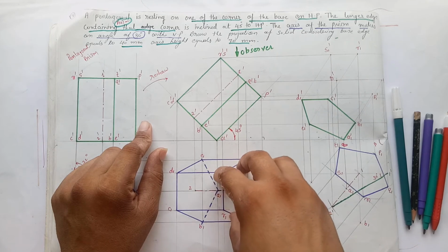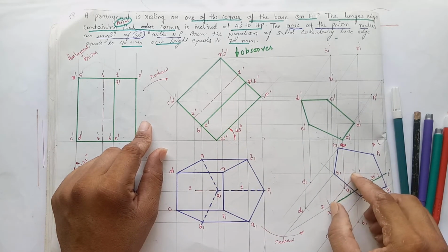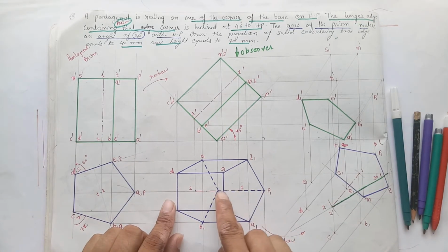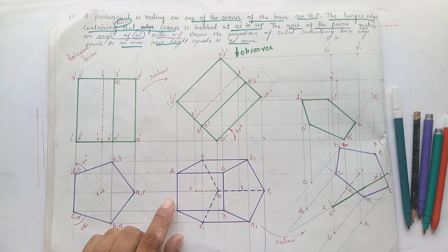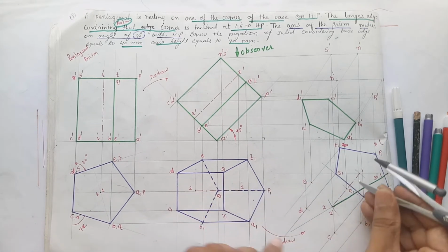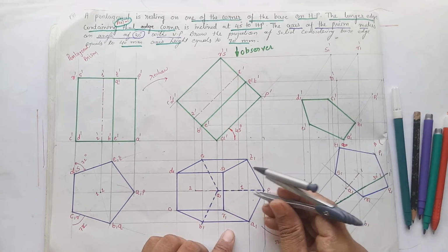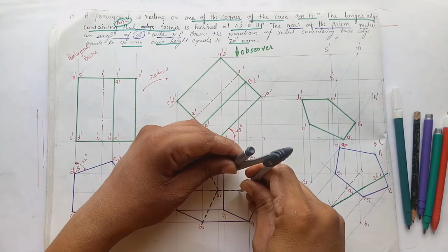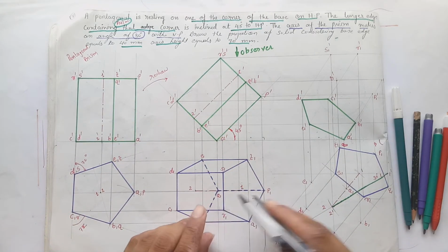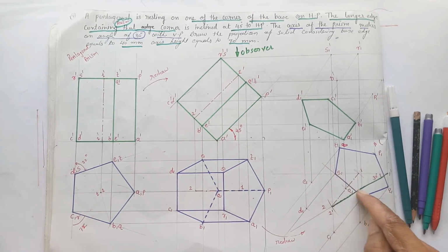So first of all, copy the top face. So here we have 1 and 2 only. So on the line of 1 we can mark P1. So measure 1 to P1. I mark P1 over here, P1. Then after 1 to S, or you can also mark this length, draw a line perpendicular to this line.